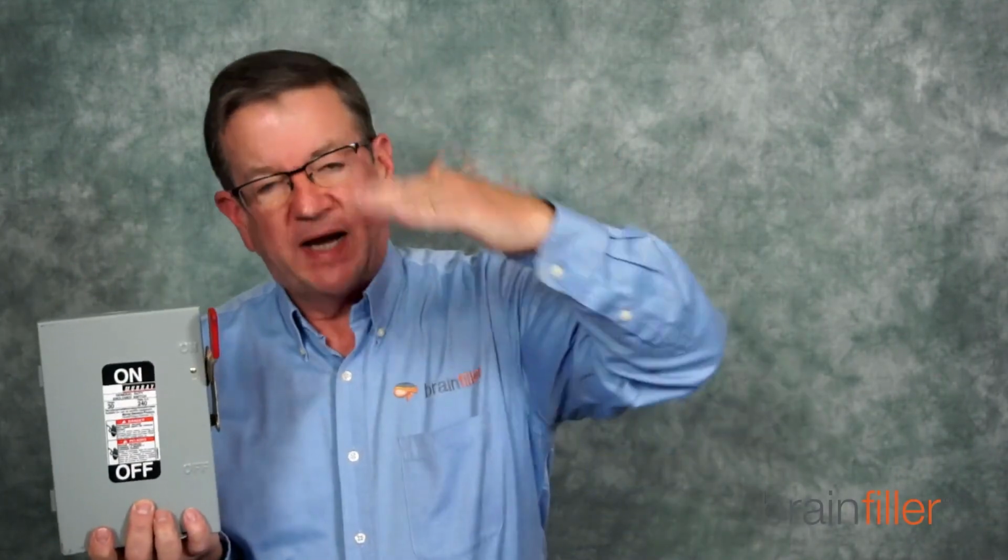Why is that? There's something called normal operation, and you can have equipment, there's boxes that you check, and if it's deemed normal operation, yes, you can operate it. There's considered to be no significant risk of an arc flash hazard. And that's just operating a switch in a normal condition.